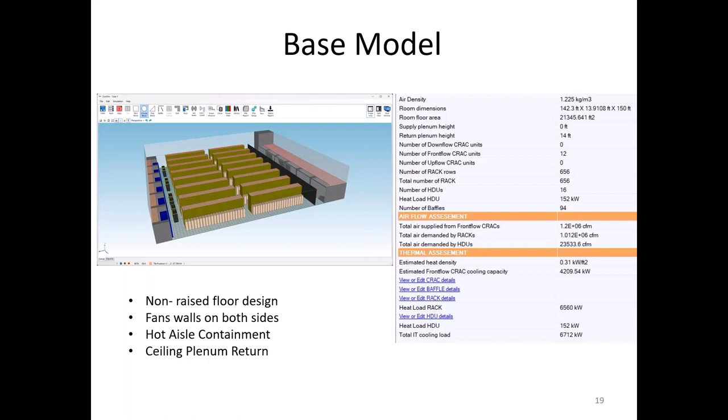I see a lot of these. What's happened is raised floors are not as popular anymore simply because of the volume. You've got so much air that you're trying to move into that room. I'm seeing rack loads here, Magnus. It's not unusual to see them. I've seen designs with rack loads in the 40 kilowatt range per rack. We're just seeing some crazy numbers. And it is related to artificial intelligence, I think, part of it, because they're all using GPUs. But it's also just more.